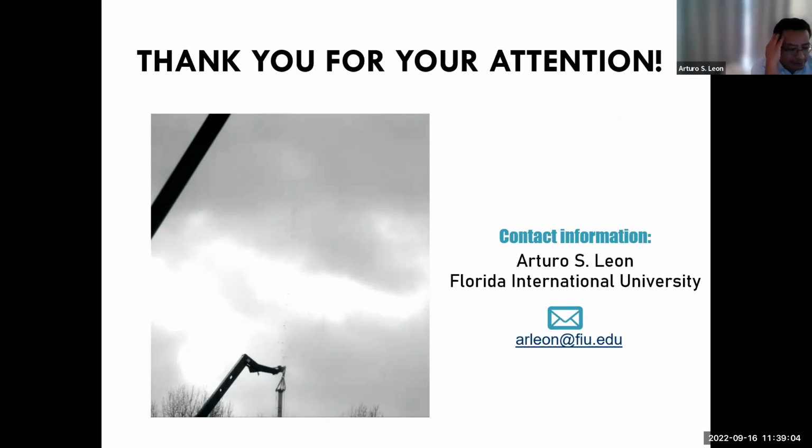Yes. There are multiple variables, exactly. If you have a big manhole, you might have two problems. First, if the manhole diameter is too small, the amount of water coming from the rain might be too large to pass the flow to the manhole or to the shaft.